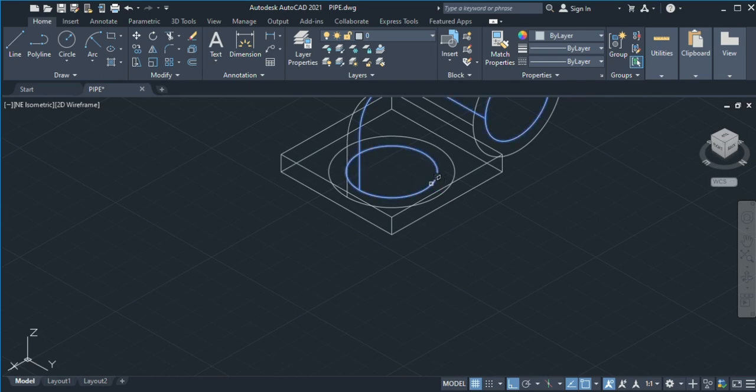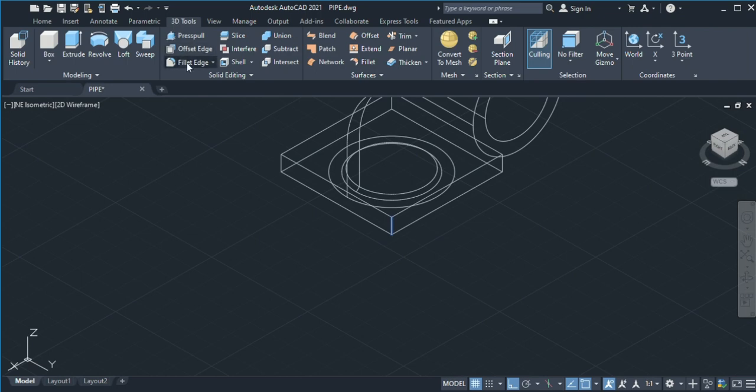That one, we do chamfer, referring to the diagram as the reference mentioned over there. C10 means that the chamfer is 10 by 10. So the command will be chamfer, then type the distance of 10. They will ask you for the secondary distance, also make it 10, then click the edges and then enter.